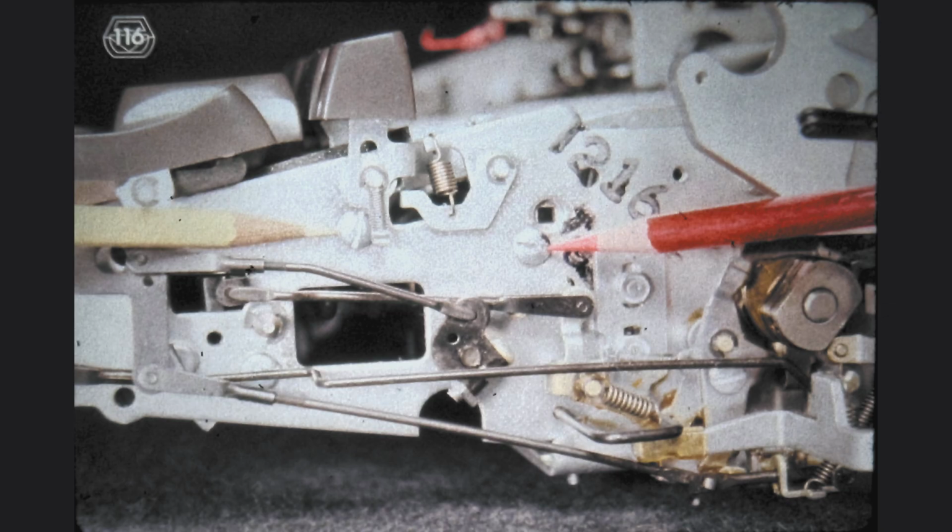For vertical parallelism, we use the cycle bail and the center lug on the interposers to evaluate it. For horizontal parallelism, we use the selector bails and the selection lugs on the character interposers to guide us during the adjustment. Take a moment now to adjust the vertical and horizontal parallelism of the cycle clutch bail and the selector bails.